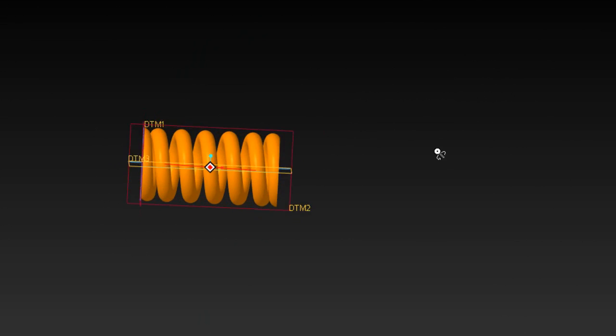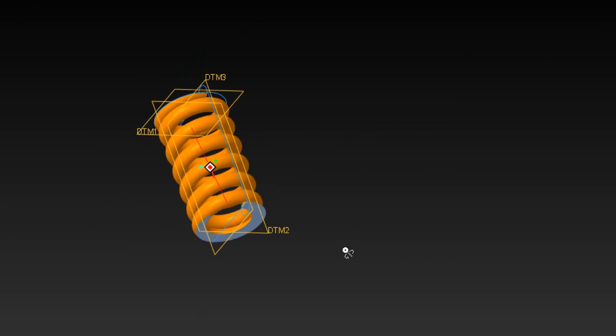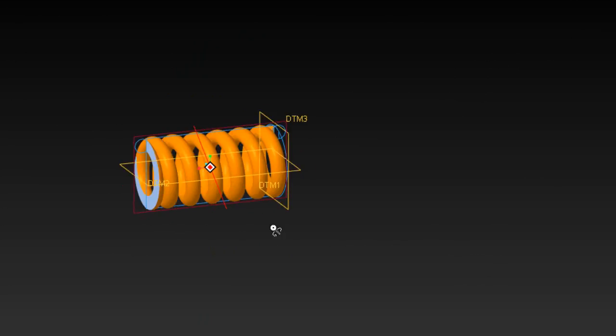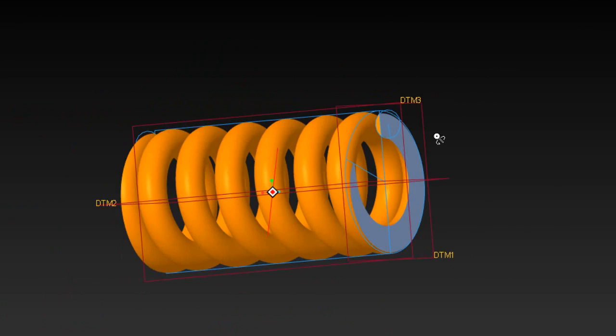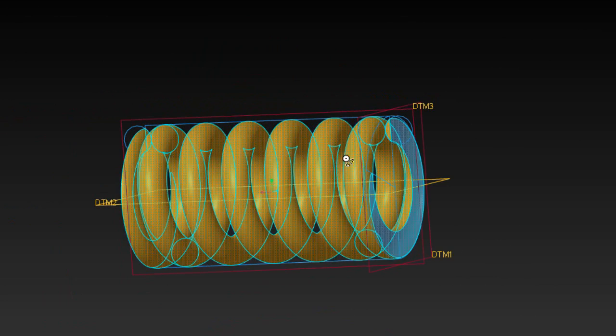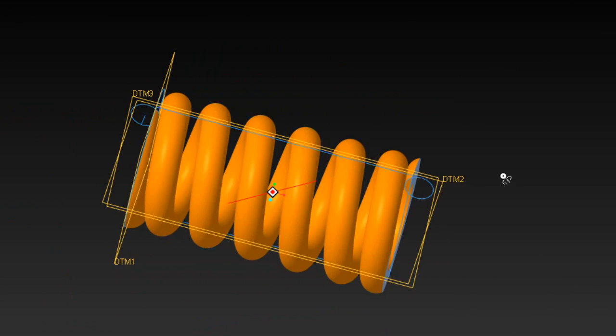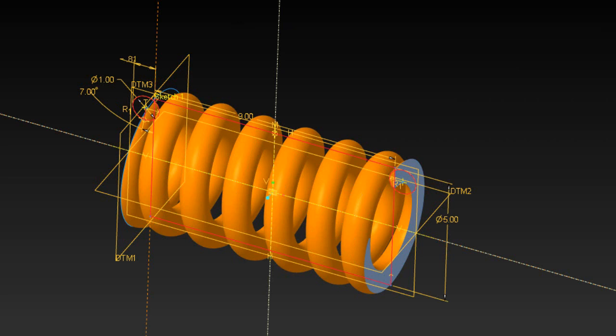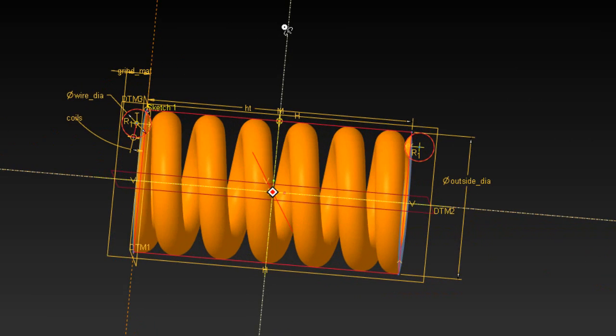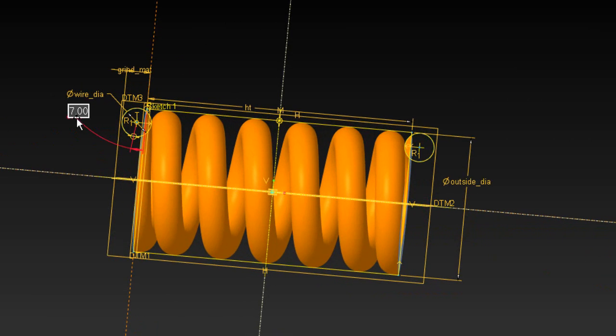As you can see, it looks like it's working, because one big clue is that these end surfaces of that coil are on the same plane. I got an even number. If I go to my sketch here and look at the coils, if I switch dimensions to change the number of coils, right now it's 7.